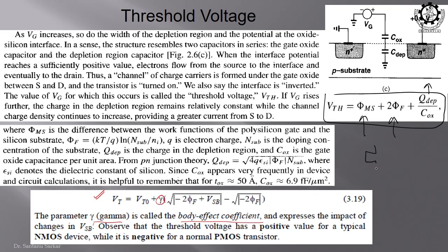So, if I have two MOS connected in series, where M1's source and bulk are at 0, but M2's source is at higher potential, which one will have higher threshold voltage? M2 will have higher threshold voltage, because of which effect? Body effect or backgate effect, clear. Why?